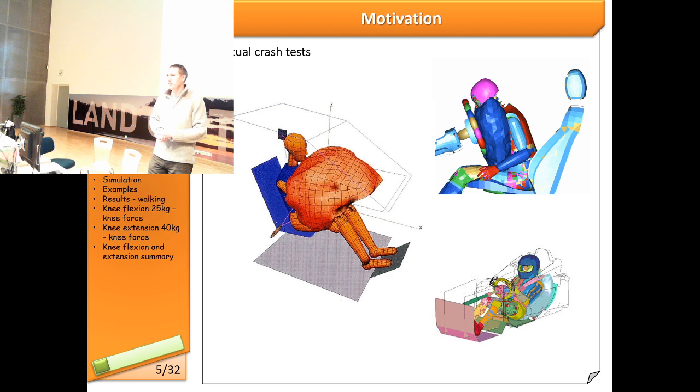So what has been done is mostly there are virtual crash tests with the virtual dummies, and everything is just simulated. The car behavior, the way how the body deforms is basically based on finite element models, and they can be more or less accurate depending on the need of the simulation. On the first trial, it might be just a model to tell whether the space is not damaged too much, but then you go to the fine detail models where you really want to know the details where the person is hitting and what kind of forces are acting on the person.